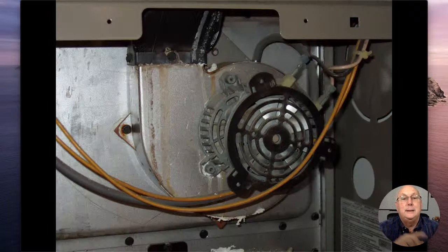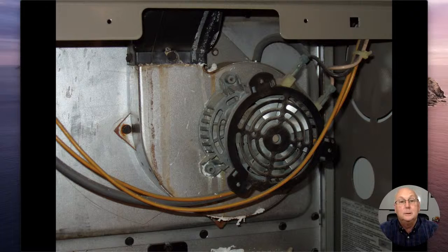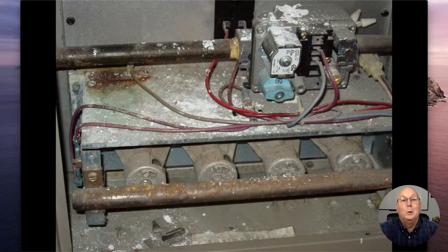Now we get up here and we start seeing the rust stains and the white condensation come back in here. You could actually see some dripping on the very bottom underneath here as well. All right. And so it's actually leaking out of the inducer fan. All that condensation's coming back. This furnace is not venting properly. All right. I should not have that condensation coming in here. And I don't want to take ownership of this problem. We're going to document this and we're going to push this off to a heating contractor. Same thing, more corrosion, more rust, more dripping. These are all things that we're going to be pushing off to a heating contractor.